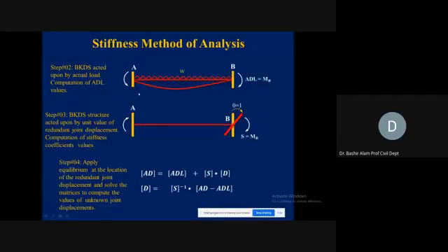Now, step 2: we expose this basic kinematic determinate structure under the actual load, which was W. This is going to be the deflected shape of this structure. No rotation here, no rotation here. So we will have some moment here because of this fixity of the support. Originally it was not there.